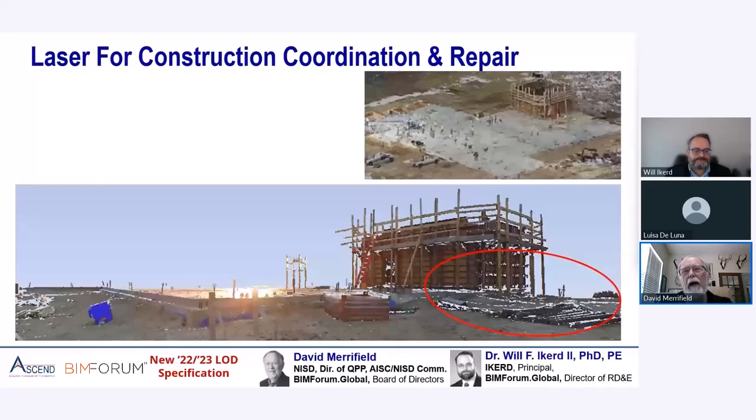Obviously, we had to go back in and establish new survey points, so our model fit where all the column center lines were supposed to occur, and the process worked very well. We treated it as a clash detection process, where we put the anchor rod scan back into the model and were able to locate exactly where they were.